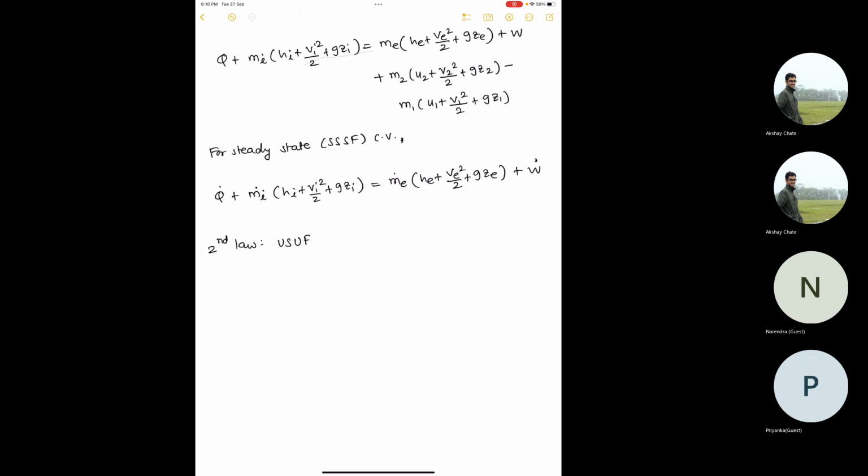I hope you remember in class the professor has derived it from Reynolds transport theorem, and there we have capital N, small n. In capital N you put the total entropy of the control volume. In small n you put small s, that is the specific entropy, and then depending on the steady or uniform state flow process, you take that d capital S by dt of control volume. That term goes to zero if it is a steady process. If not, you do the time integral over certain uniform states, so 2 and 1 subscripts are used for that.